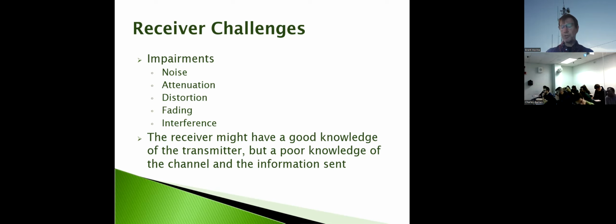As it propagates longitudinally away from the antenna, it's spreading out more and more. So there's an R squared at least dependency on the wave magnitude. So it attenuates, even if it's not going through any lossy type of media, right?